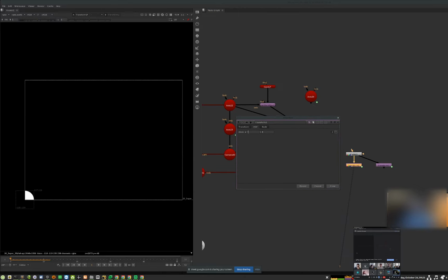And I'm giving it a grid 4x4 in this case. And what it will do is go 1, 2, 3, 4, 1, 2, 3, 4, 1, 2, 3, 4. It will basically move a camera in this area light to sample it, in this case 4x4, 16 times in this kind of sampling area. But I'm going to do it in all sub-frames, so all 16 samples will happen in one frame. And this guy will just control that.